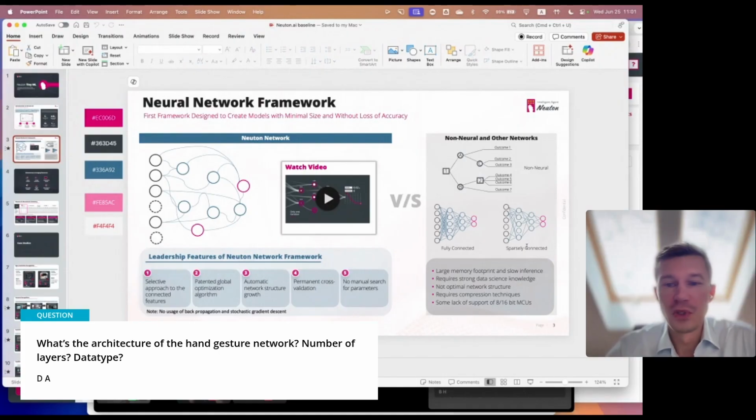Okay, let's say you've done a few iterations with different architectures and you've trained the model that satisfies your accuracy criteria. And then you go ahead and start compressing it: pruning, quantization, compression, convert it in TensorFlow Lite Micro, and start using this. And it performs well, but you never know how many nodes in this neural network are redundant. We have seen in our studies examples of 50% of nodes being redundant.